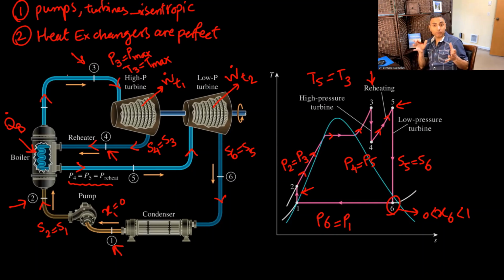So looks like if it's an ideal cycle, if you have these four pieces of information, which means P1, P2, P4, and T3, I can solve the whole cycle because it's supposed to be ideal. There is no pressure loss. All the pumps are isentropic. What does that mean? It means the efficiency of the pump is 100%. Even if it's not 100%, you can still solve it. I have a video over 40 minutes about how to solve the pump work when it is not an ideal pump. You can watch that video for the cases that the efficiency of the pump is not 100%. For this case, the efficiency of the pump is 100%.